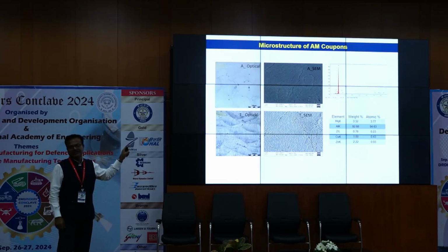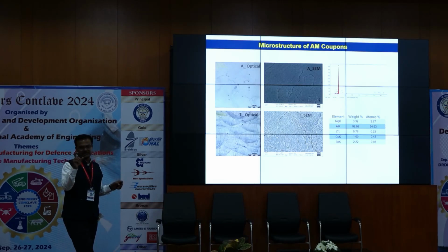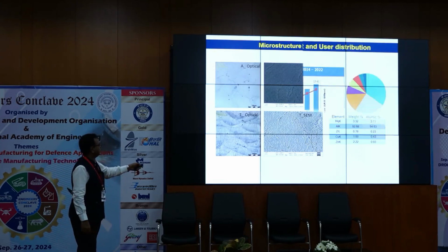This essentially contains zinc, so maintaining zinc within that range is another challenge. When you are heating up and atomizing, there will be a lot of loss of zinc. And even with a little tinkering with the zinc composition, you end up with solidification cracking.